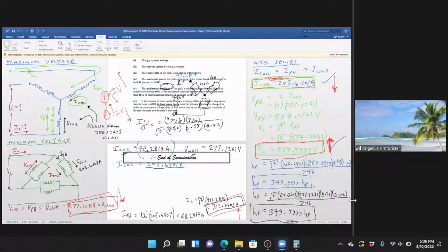And when you change the taps on the primary, as you make the taps on the primary lower, you convert the transformer to more of a greater step up transformer. Every time you reduce the turns, you reduce the primary in comparison to secondary, the transformer steps up more. That's how power systems work. That's how BC makes the voltage higher or lower. You go up on the primary, you decrease the output voltage of the secondary. You go down on the primary windings, you increase the output on the secondary voltage.